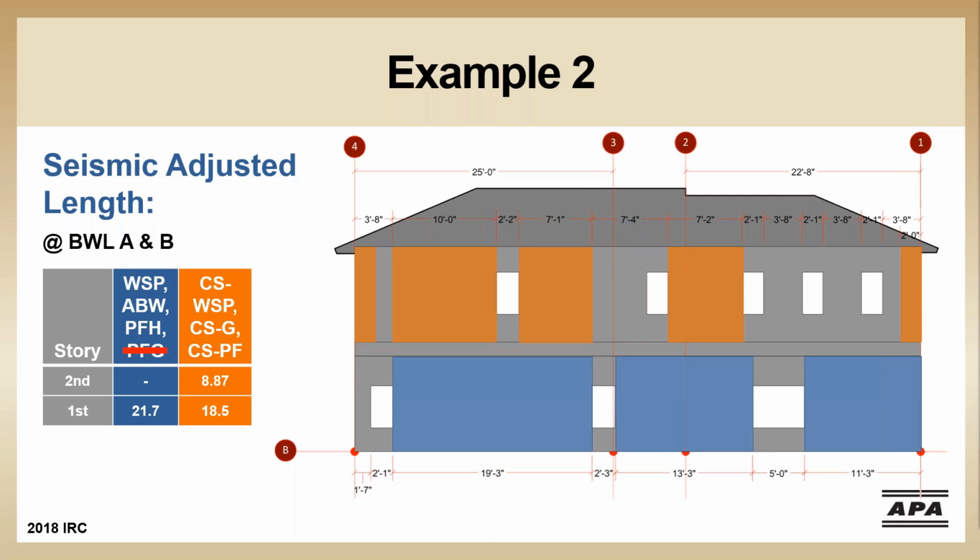Last wall line, hopefully we've got some steam going and we can spot issues and opportunities a little bit faster. Right away, we can see there's not a return wall on the ground floor at braced wall line 4. So let's add a hold down. We easily made the 4.83 foot requirement between braced wall lines 1 and 3. We're missing a braced wall panel within 10 feet of the left end though. So let's add the full length of this end panel.